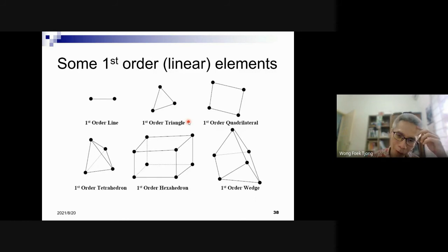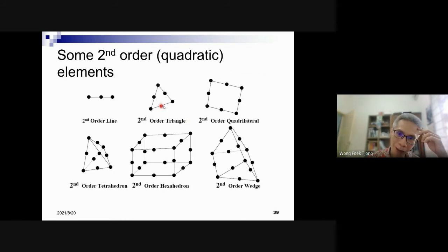But if the software has quadratic elements, actually the elements can be curved. We can move the node outside and it becomes a curve, because quadratic is a parabolic curve actually. If the shape is circular, of course, this is also an approximation. Circular approximated by parabolic, a different curve, but it's better than a straight line.